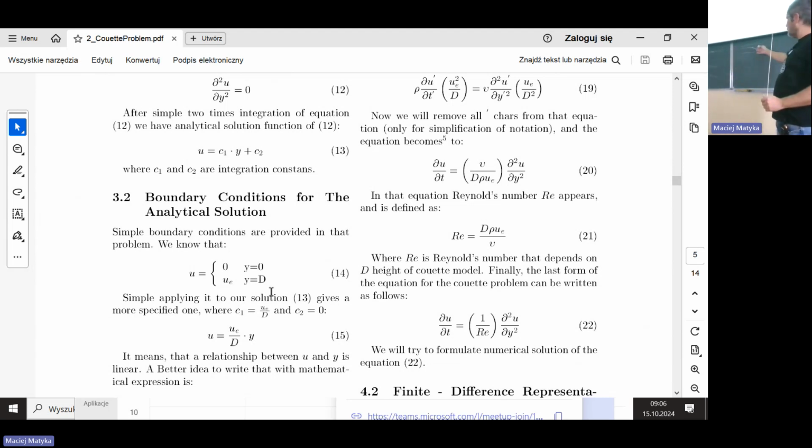But anyway, so that is very hard. What people do very often, they scale the problem, because what matters is the Reynolds number. And as you know, the Reynolds number is proportional to the size of the system. Now, if you scale down this car 10 times, so let's say it will be 10 times smaller, then you can use a model which is 10 times smaller.